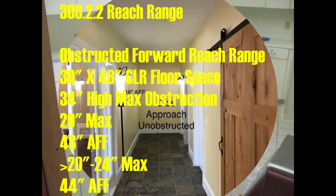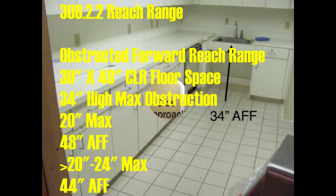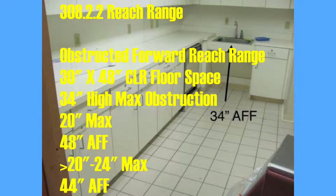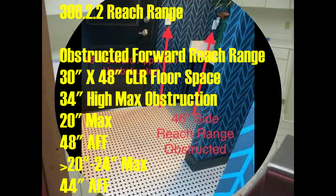Obstructed forward reach range with the same clear floor space. The obstruction can be a maximum of 34 inches above finished floor. 20 inches deep maximum, the reach range is 48 inches above finished floor. Between 20 inches and 24 inches deep, the reach range is 44 inches above finished floor.